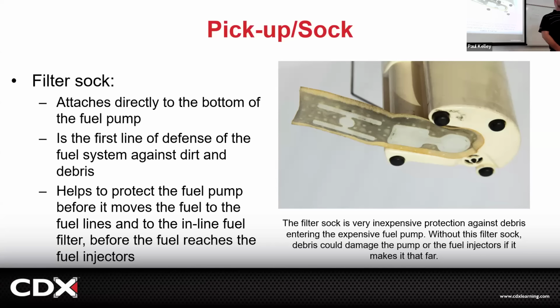So when you don't have enough gas, you're like, is it the fuel pump electrically? Maybe it's the sock? But either way, guess what? If you're getting a fuel pump, it comes with the sock. So you would have diagnosed it well, and then you pull it out and be like, oh yeah, the sock is all full of stuff. If the sock is all nasty, you better clean the tank too, though. And then you might talk to the customer and be like, hey, did you dig this fuel out of the ground and shovel it into your car? Where'd all this debris come from? You know what I'm saying? Because you don't really want that in there. The sock has a limit to how much debris it can catch.